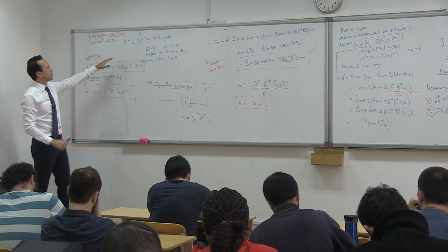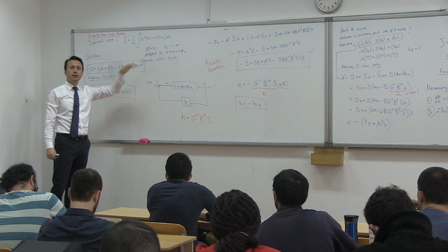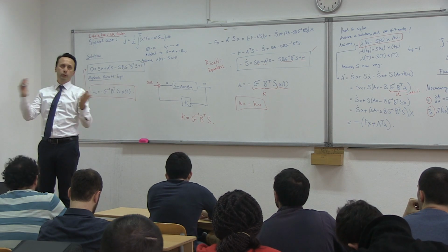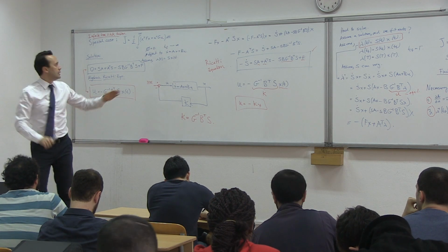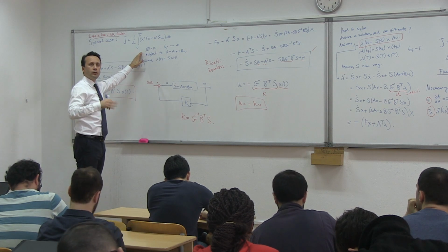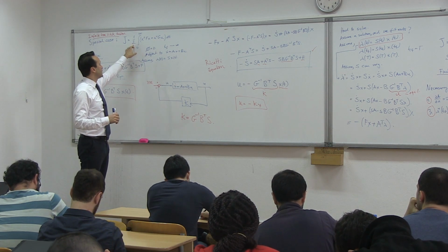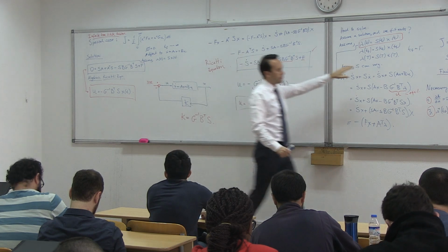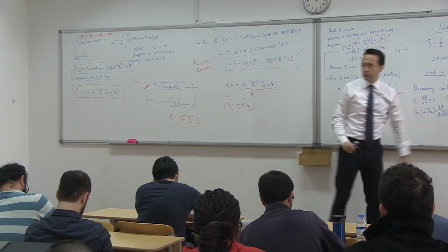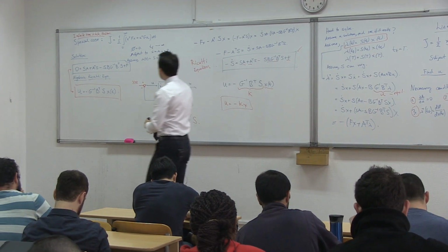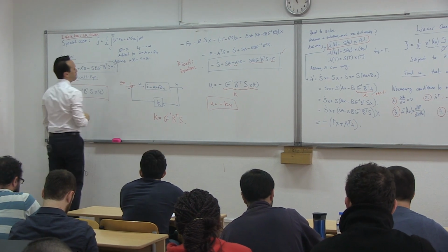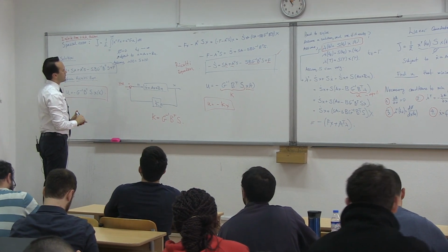Change the problem a little bit, remove the terminal constraints, so no guarantees on the terminal time. Okay. There could be steady states and all this, no guarantees on the terminal time, so that's gone. That's not part of the optimization problem anymore. Phi is equal to 0. And t final goes to infinity. Okay, we take that to infinity.